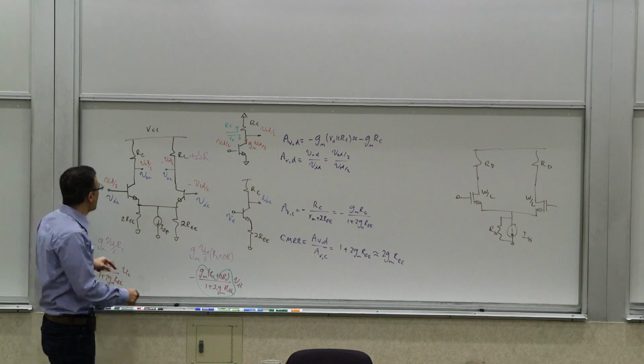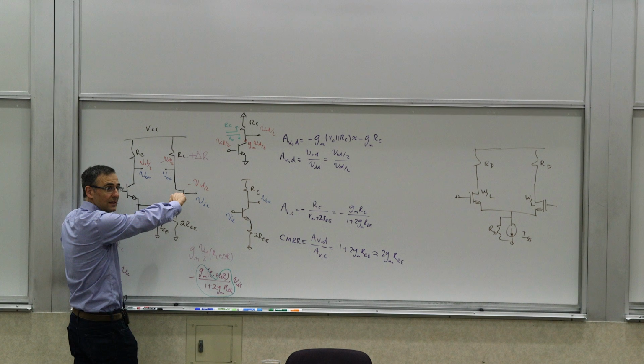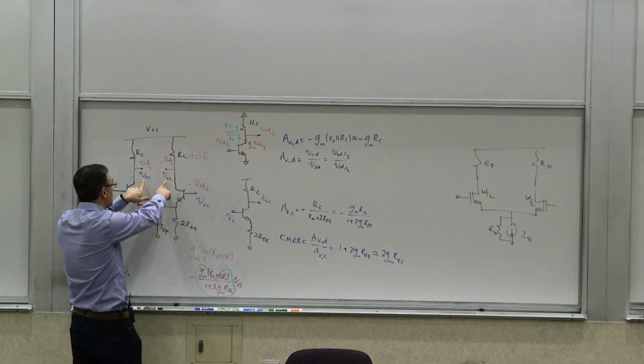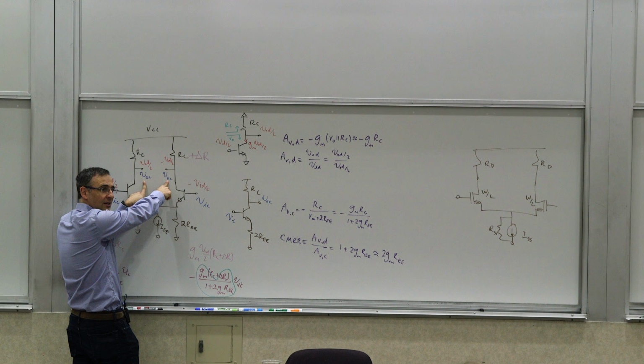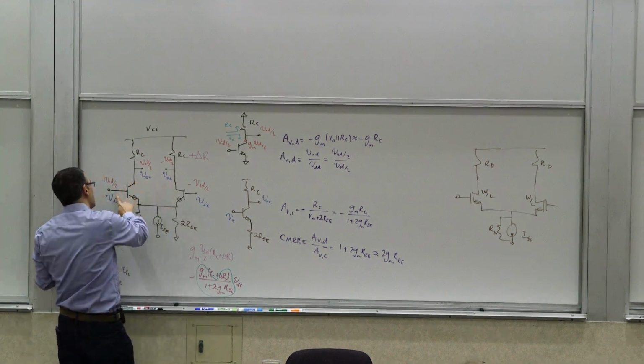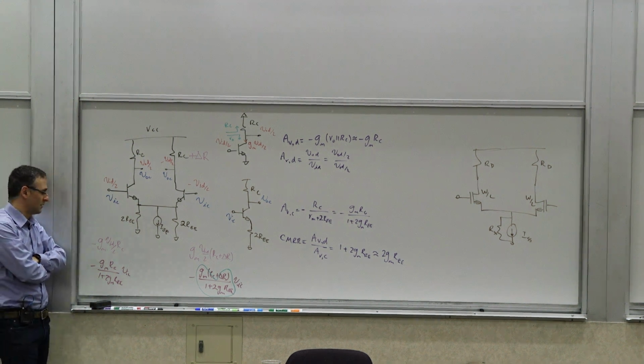No, but remember, in a common mode case, the output voltages are the same if you had the ideal case, right? If this is going up and down, this is a symmetric mode. So the two VOCs are the same. So the common mode gain is defined as the ratio of VOC to VIC. So you're not going to take it.